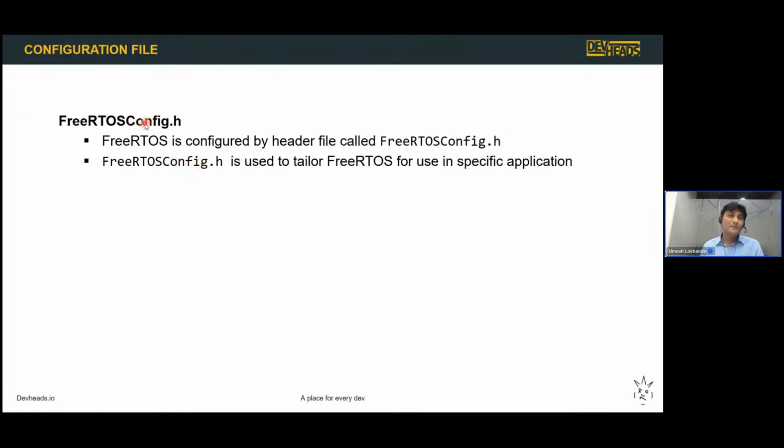All right. Let's say I want to configure my FreeRTOS kernel to use a preemptive scheduler. So I'm going to enable the macro for the preemptive scheduler because I don't care for the cooperative scheduler, right? This is the way you can use this configuration file to configure your FreeRTOS kernel to fit into your requirement, right? Isn't it amazing? This file is everything. If you understand this file properly, you understand basically most of the components of FreeRTOS.